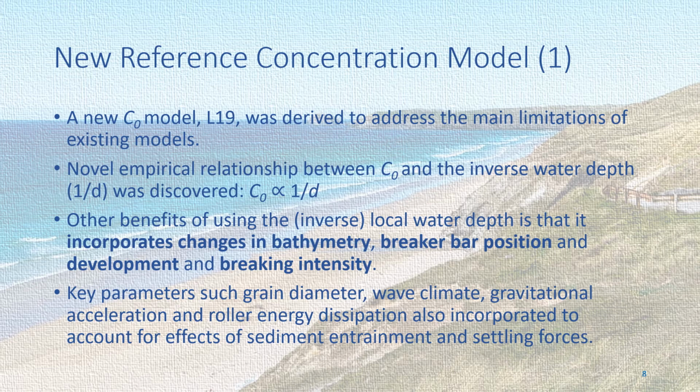Some of the benefits of using the inverse local water depth is that it incorporates the effects of bathymetric changes over time, the breaker bar position and development, and also the breaking intensity. The reference concentration was also found to be a function of the sediment properties, wave climate, entraining and settling forces, and more. Therefore, key parameters such as the average grain diameter, wave climate, gravitational acceleration, and roller energy dissipation were also incorporated to account for effects of sediment pickup and settling forces.